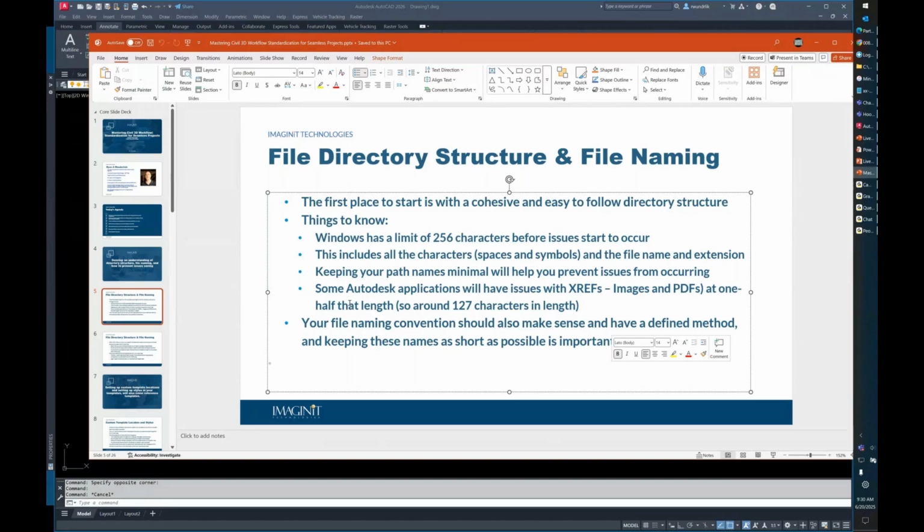Oh, your files are on a jump drive. An EDU license, that should not be an issue. It's something specific either to your jump drive or something specific to the drawing. If the drawing did not get copied over correctly, that bitmap that you see, which is a preview, is actually a stored image in the DWG header. So your DWG file is made up of a snapshot of that image and other data. You may still see the image. The actual drawing could still be corrupt or broken or incomplete. So those are all the things that can cause that if those files are on a jump drive. But that's a very good question.